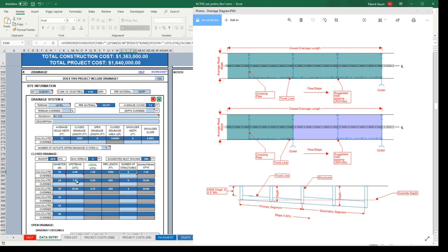So then we just add the local upstream, do the same calculation we did before. Again, 826 linear feet of trunk line we can place with that 24-inch pipe and take in that additional area. The downstream will basically be just the 7.45 plus the 8.59 will be your downstream flow going to the next, or 30-inch pipe.